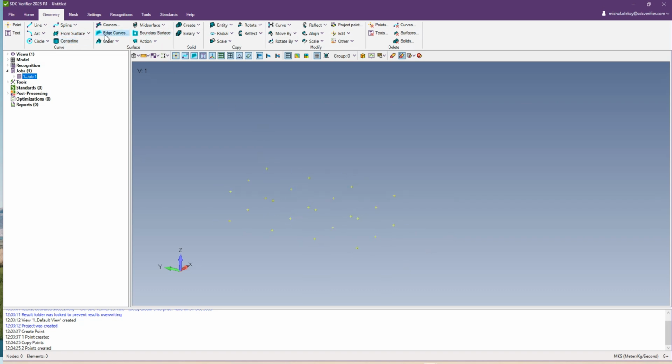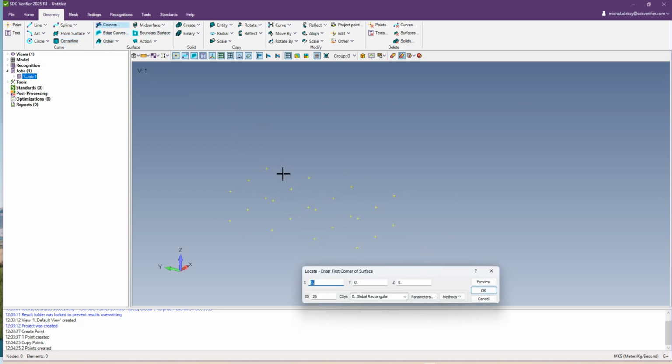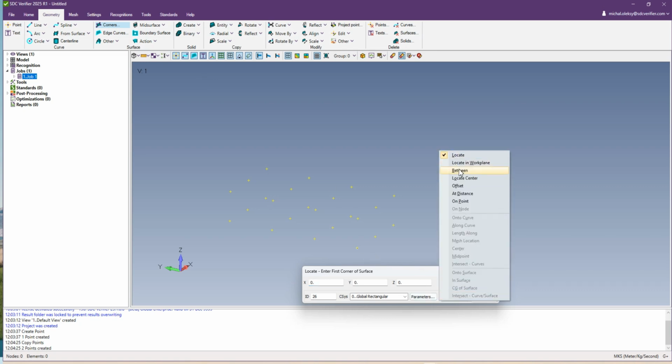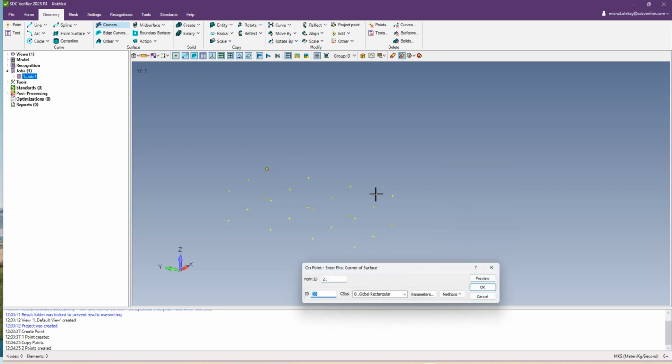Now we can proceed with creating the surfaces. Here we can create them with use of points. Set the method to point and pick the first point, OK, or enter on your keyboard, second point, enter, third, fourth. The first surface is created. Then let's create a perpendicular one.